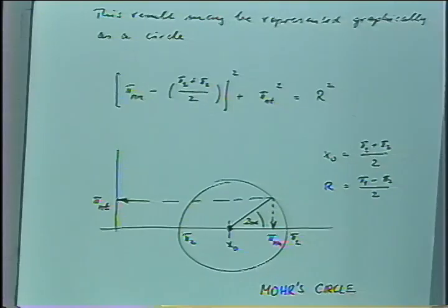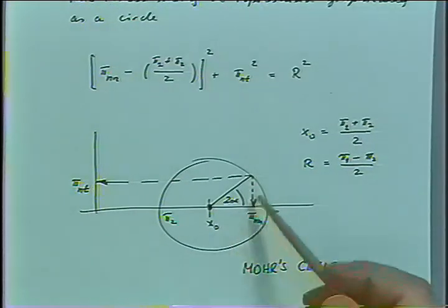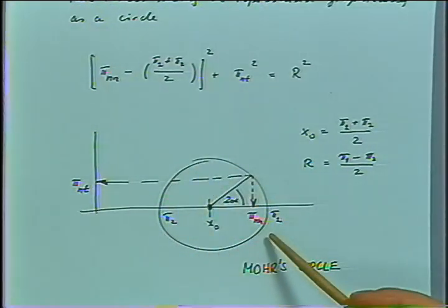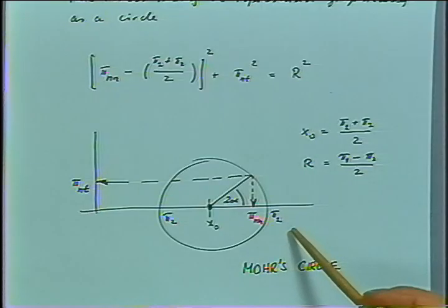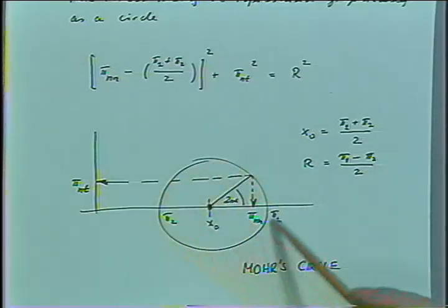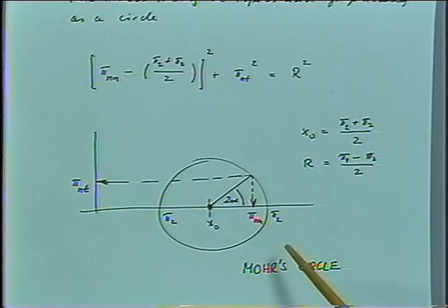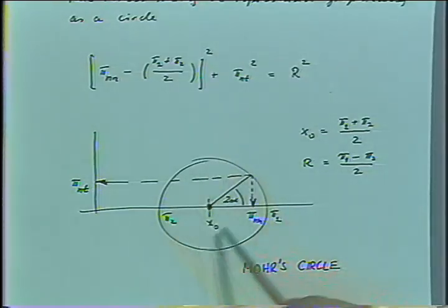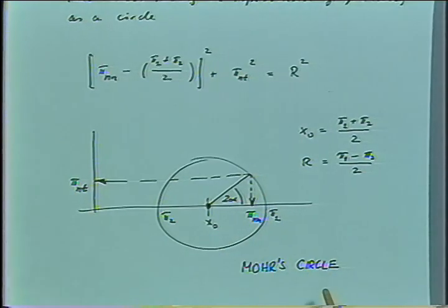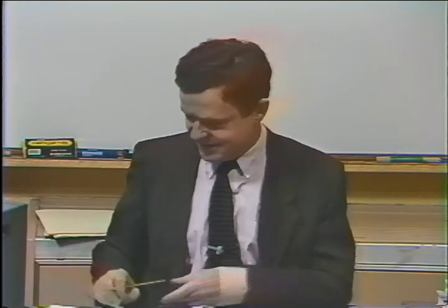So in the absence of computers, and maybe also in the absence of training, you could give this graph to people who are building bridges, for instance. You tell them about the stresses in certain situations, and they drew those circles, and they calculated the angle dependence of shear stresses and normal stresses in a convenient way. So this was more a historical excursion here in talking about Mohr's circle.